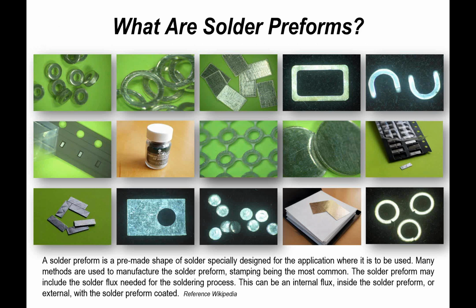But generally speaking, when we talk about preforms, we're talking about solder preforms using traditional alloys that have been well used in our industry for many, many years. But what a supplier will do is specifically design a preform for an application. So the benefit there is you get a consistent volume of material for the particular operation that you're trying to conduct.